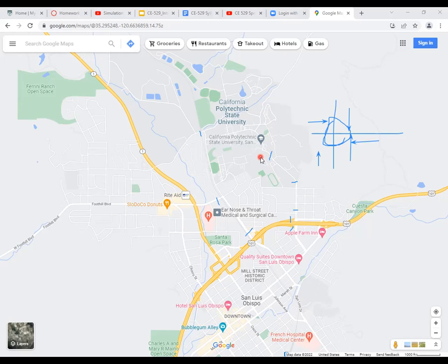What other data? We talked about the speed, we talked about the traffic volume. What else? Yes, Tim. I thought the roadway geometry would be important. Yes. So you could maybe do geospatial data with the roadway. That would have the number of lanes, the turning movements available, sometimes speed limits, or the traffic signal. Yes, signals. So basically all sort of geometric design data, right?